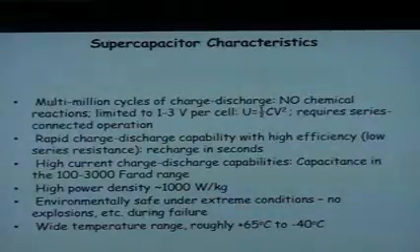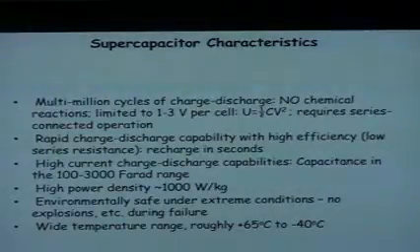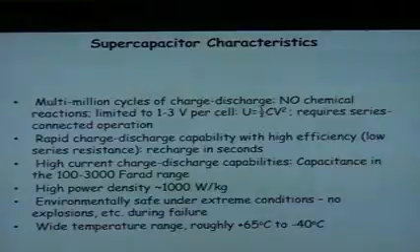supercapacitors tend to be more friendly for temperature extremes, and I'll have an entire lecture about that as well coming up. But you can go to very, very high temperatures. So here in Jodhpur, right, you could be operating in the hottest day of summer, which I'm told is near 50 degrees C, which is, wow, that's really, really hot. I don't know how you can even do anything when it's that hot outside. But more common to me, or familiar to me, is the minus 40 degrees C, right? And neither of those temperatures are suitable for most batteries, but supercapacitors can handle them pretty well.